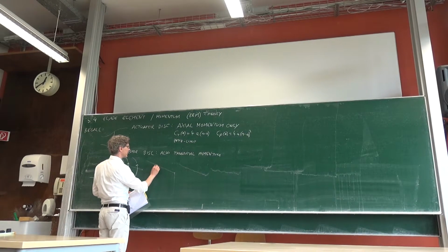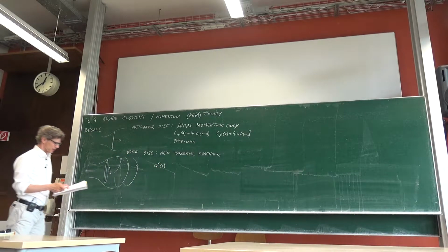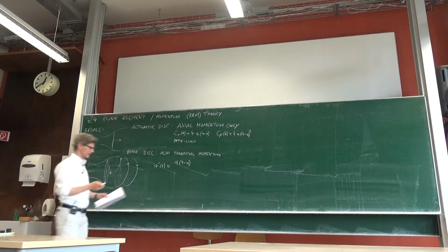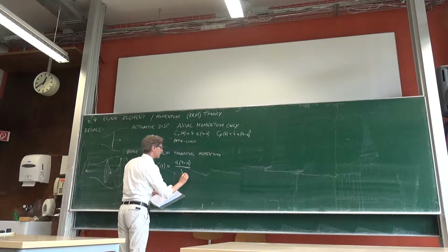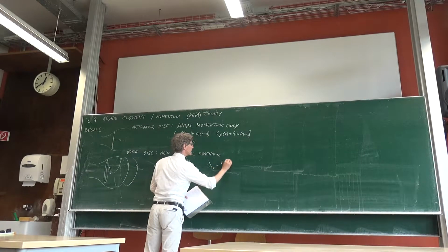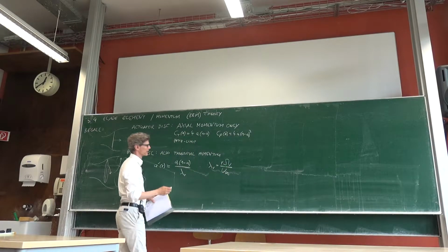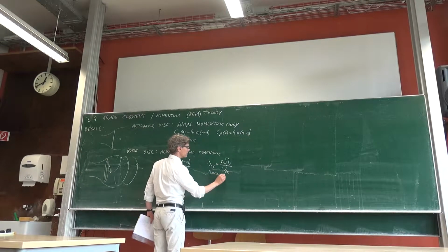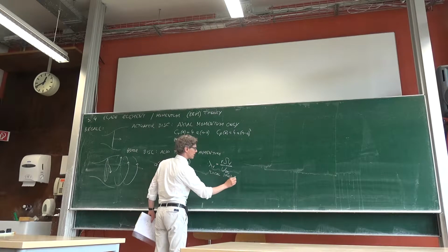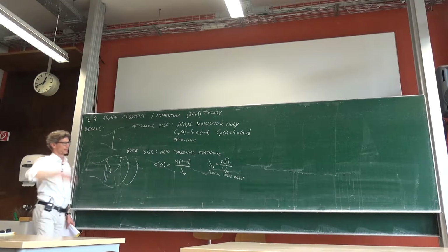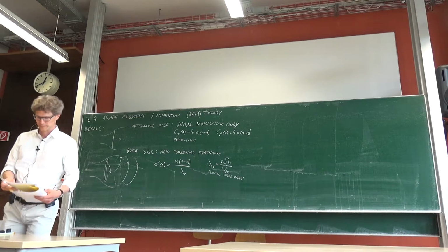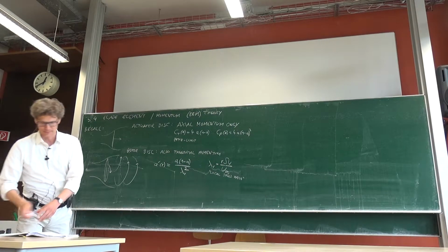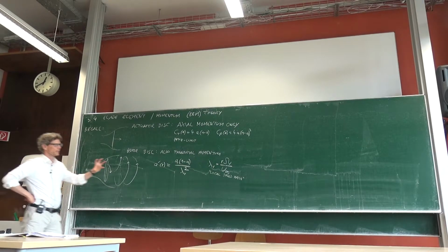So then we derived a formula where we bring everything together that we had, and it's actually a prime equals a, the induction that we had, times 1 minus a, and then divided by some number, and this number I want to call lambda r squared, and lambda r is r times omega divided by u infinity. It's not the tip speed ratio, but it's a local speed ratio. Yeah, local speed ratio. How much faster do we move with our disk than the wind at a certain location? Is it lambda squared? Oh yes, thank you very much. Great. Wonderful. So this is what we derived, and only by looking at tangential momentum and the energy balance.